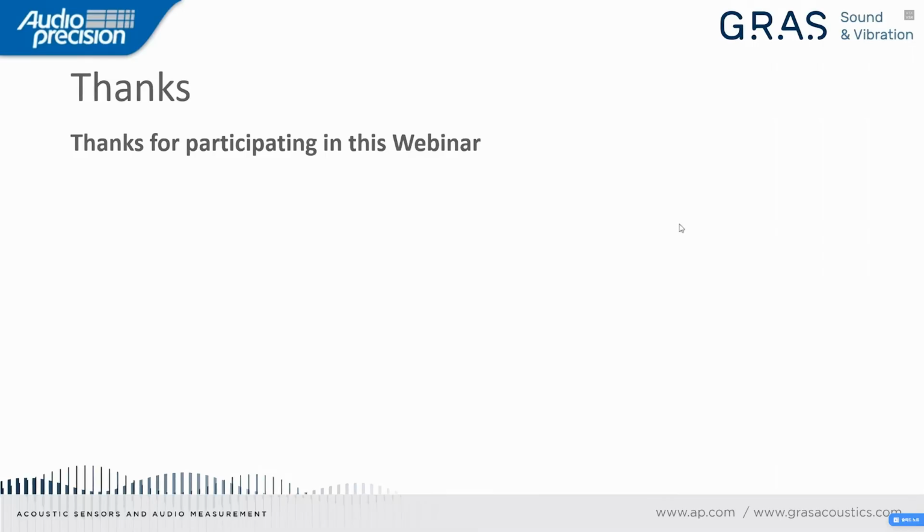We have one here. What will the process be for measuring directivity patterns, both of the acoustical output and of the microphone array? For measuring the directivity, you need the microphone array to be turned around. You could use a turntable, so the microphone array will turn around your reference speaker, your mouth simulator.